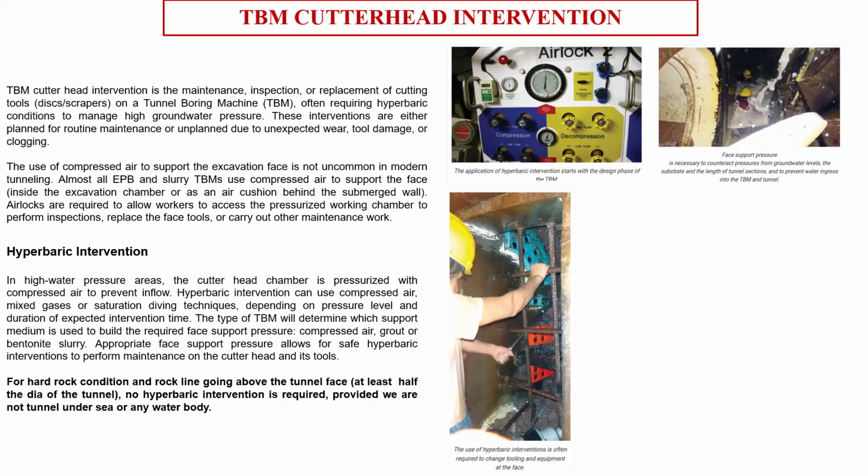So the face pressure application also depends on your type of ground, the cover above the ground, and what type of structures are lying above it. What is your penetration rate? There are lots of things taken into account when the face pressure is applied. But the process starts from the designer. The designer gives an idea about the face pressure as per the ground condition, but from the operation point of view, the contractor finally decides what amount of face pressure he will apply.